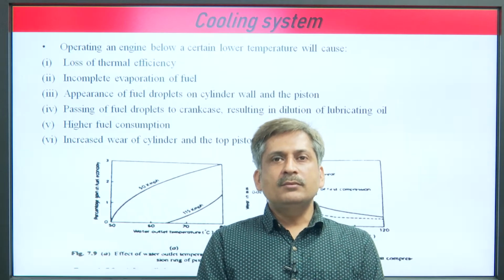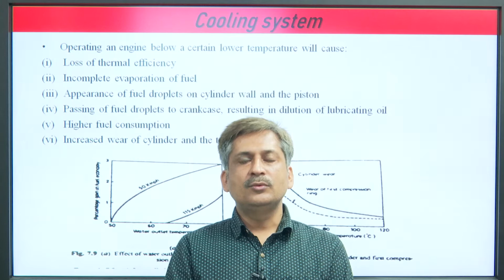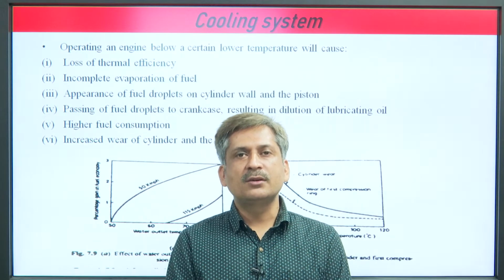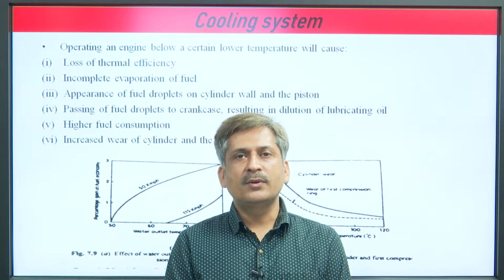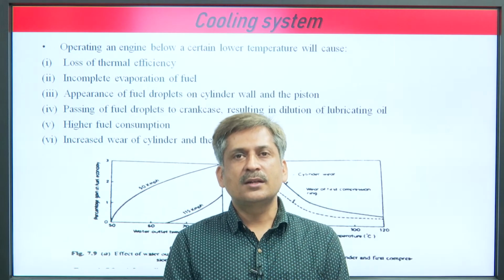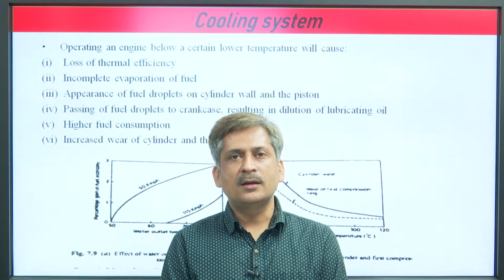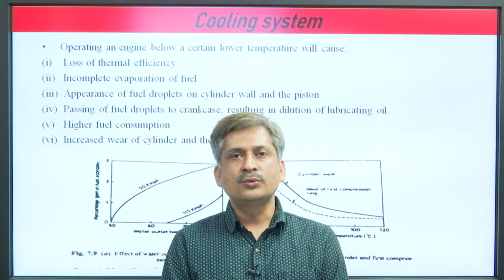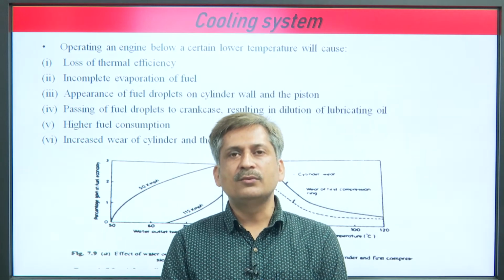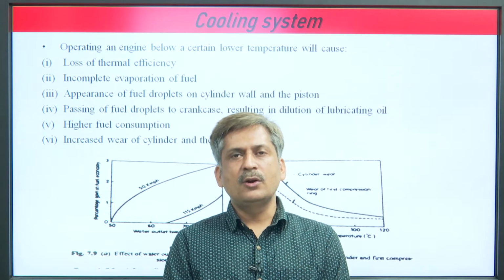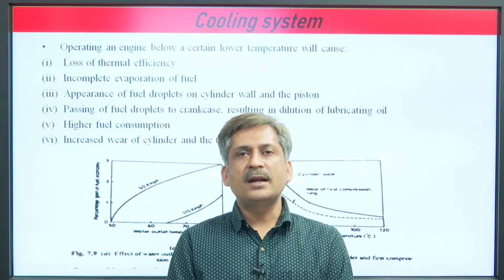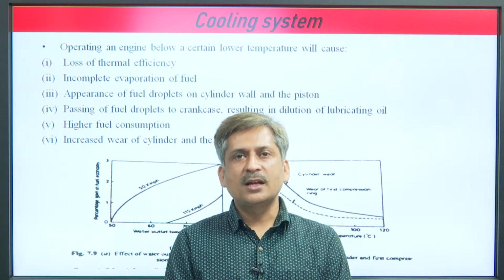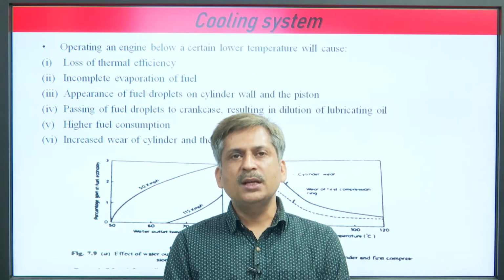So, why is engine cooling needed? Mainly for two purposes. One is to protect the lubrication film around the different components, so that engine friction is controlled, and another is to sustain the metallurgical limit of the engine components. If that does not happen, the engine may seize. So engine cooling should be there, but at the same time it should be effective also.